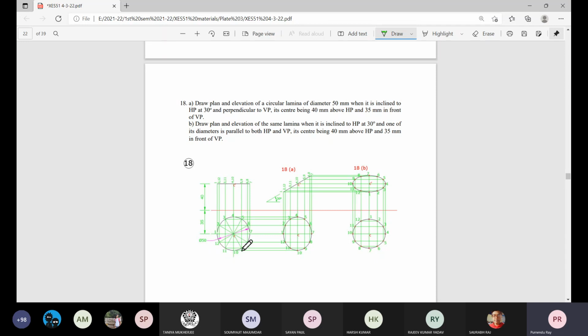But this curved line is a continuous curved line, there is no straight part. So we assume it to be a combination of 12 very small straight lengths when we subdivide it uniformly at an angle of 30 degree and give the point names. And finally you will get almost that ellipse when we consider these 12 points.